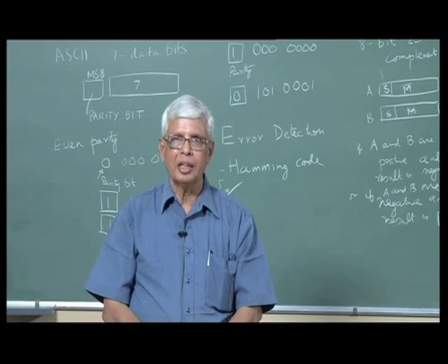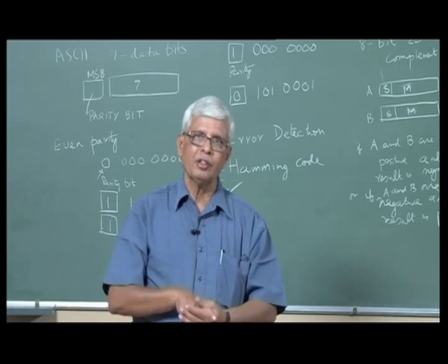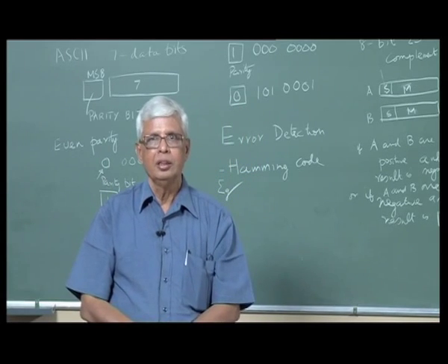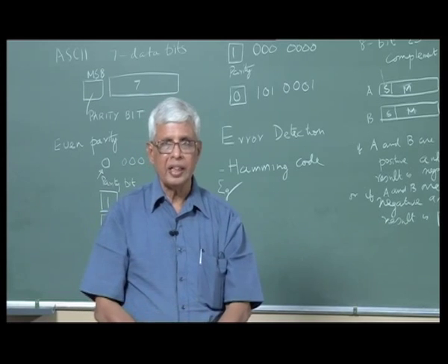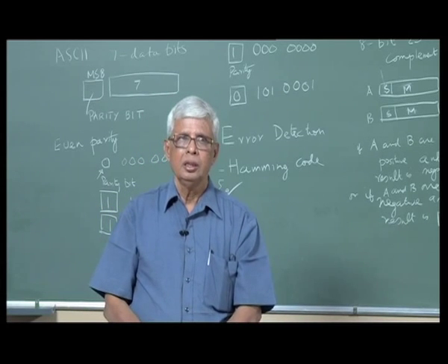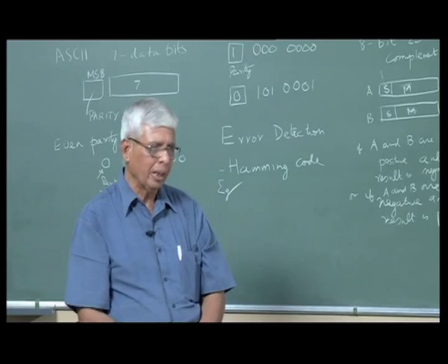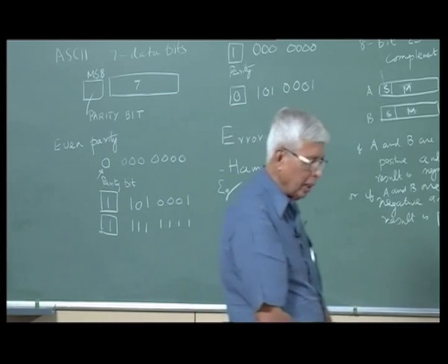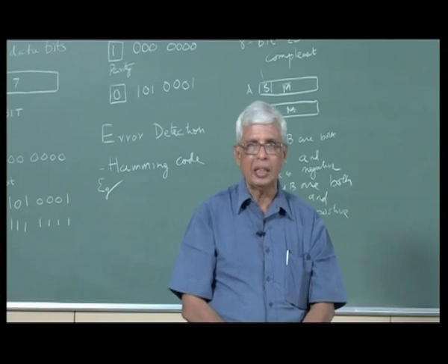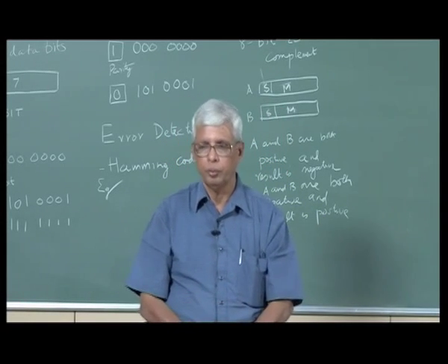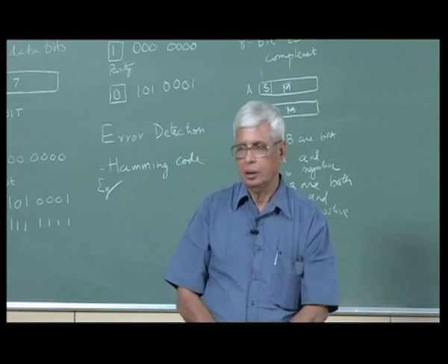Overflow error will not be there, but since you have divided everything by 2, finally when you take the result, you multiply by 2 and take it as 200. That is one technique. This overflow error is because you are trying to push in a number which is larger in magnitude than the magnitude capability of the register into which the result would go. How do you detect it?